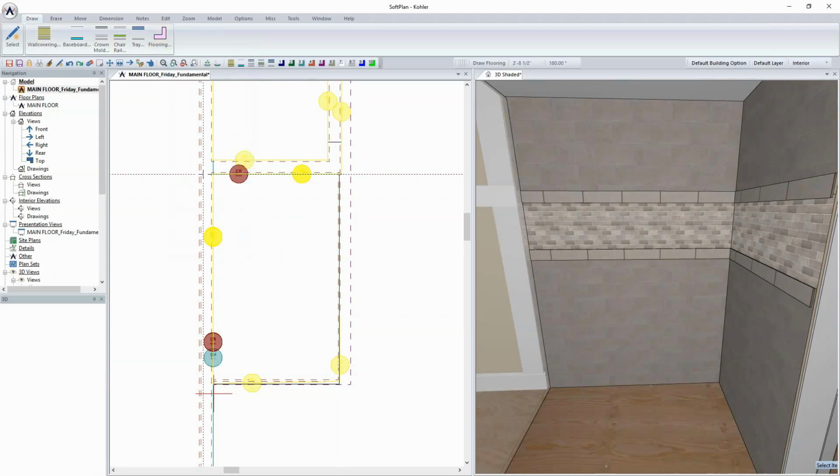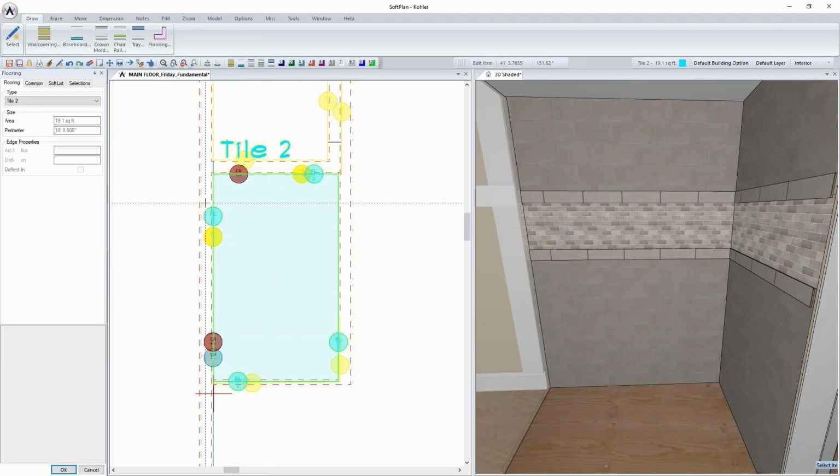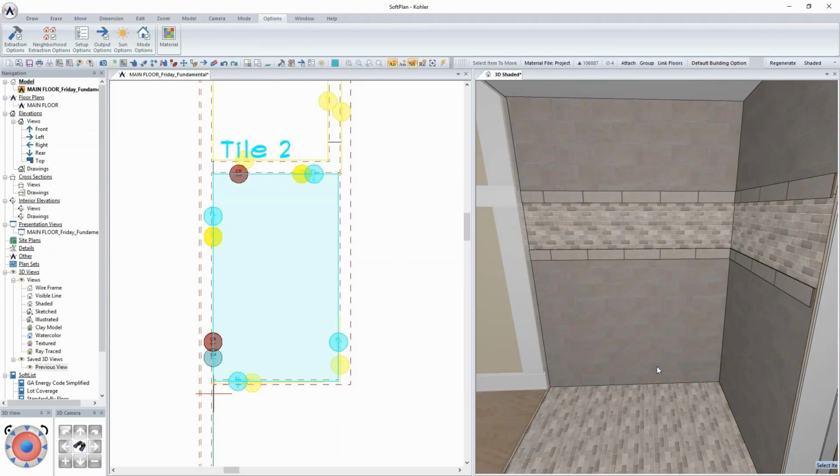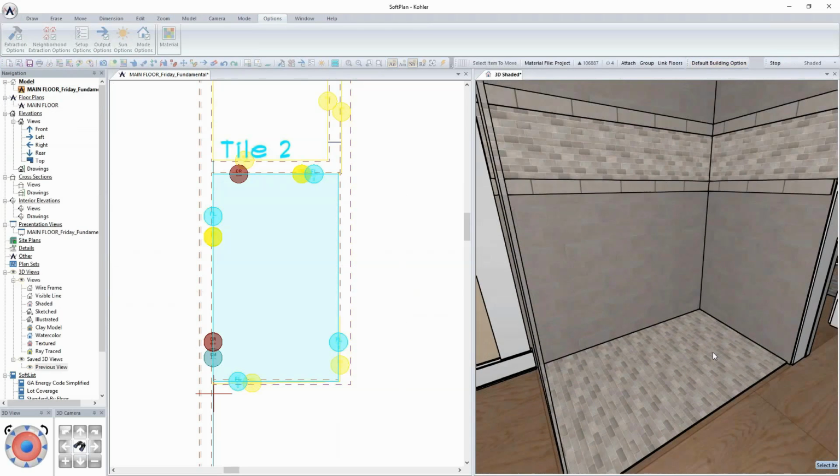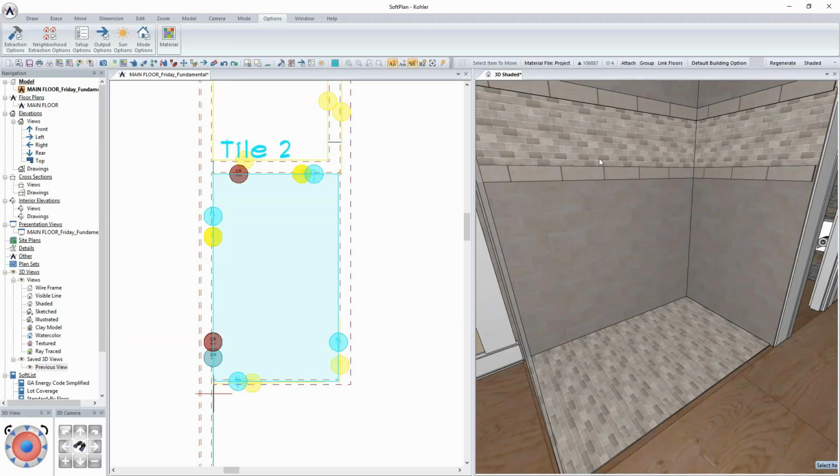And what you're basically doing at this stage is you're just drawing a polygon. You have to enclose the shape in order to place it in there, and as you edit this, it will tell you what tile number it is, what the square footage is, etc. And again, as I go back and forth between the two, keeping in mind I've turned the glass off on this at this stage, I now have basically a similar texture that's being used on both of these.